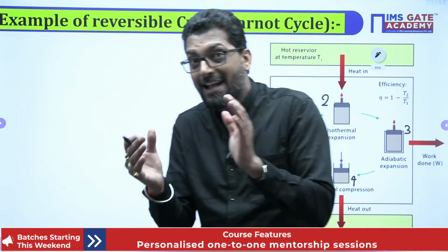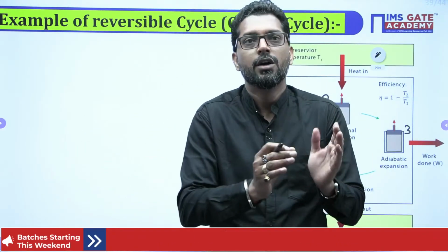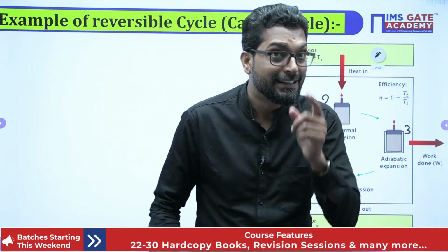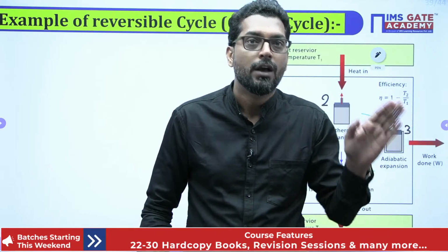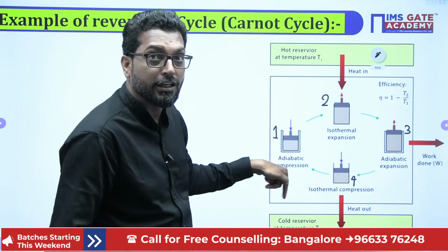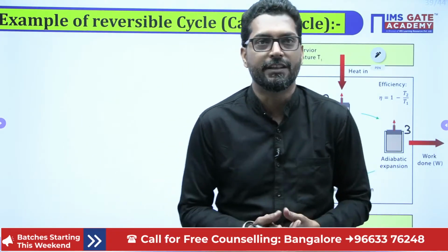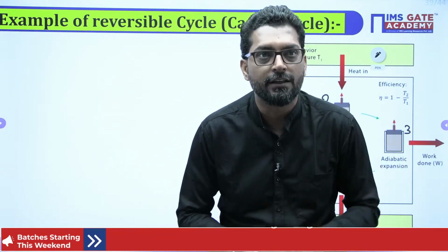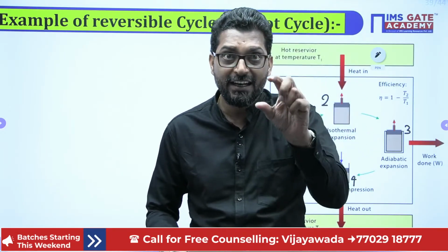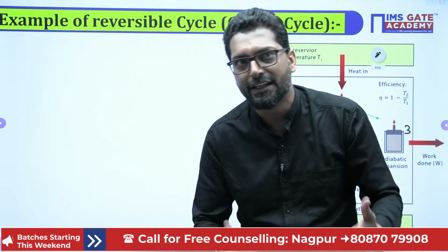So you apply the first law of thermodynamics, del q is equal to du plus del w. In that case, the heat transfer is 0 and the work is negative. That means the work input is negative, so its internal energy will increase. That means pressure increases, volume decreases and internal energy increases.